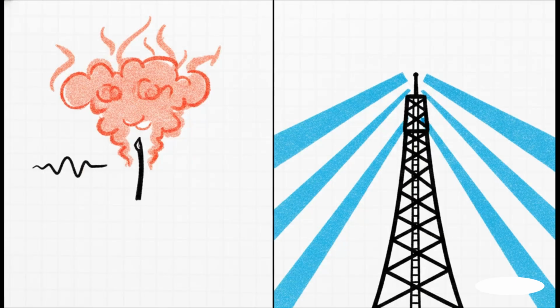Think about what that number means practically for engineering. Because that radiation resistance is so infinitesimally small, less than 1/100th of an ohm, it acts almost like a short circuit. The natural resistance of the copper wire itself will actually be higher. Thus, almost all your expensive transmitter power will just burn up as heat in the wire, that's ohmic loss, rather than radiating out into space. This math perfectly explains why AM radio stations operating at long wavelengths simply cannot use small antennas. They are mathematically forced to build those colossal, towering structures you see out on the horizon.